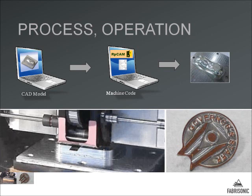So what we have is a product we call SonicCam. SonicCam takes a 3D model, slices it into layers, and creates the G-code needed to drive the machine. In the background of SonicCam is really a software package called Delcam. Delcam is a commercially available CNC machining program that has several 100,000 seats available worldwide. Delcam is used to tell a CNC machine where to machine away material out of a solid block to make a part. It says, I have a 1-inch end mill, I want to take 6 thou layer off, and it has algorithms to figure out where to move that 1-inch end mill to make the part that you want.